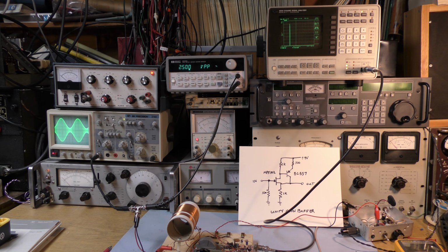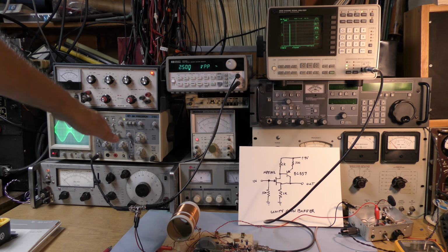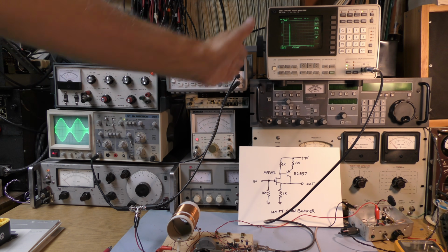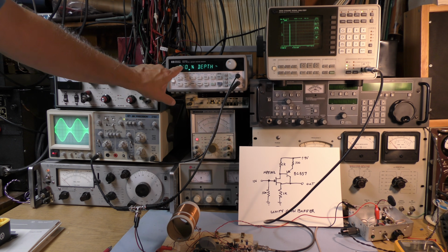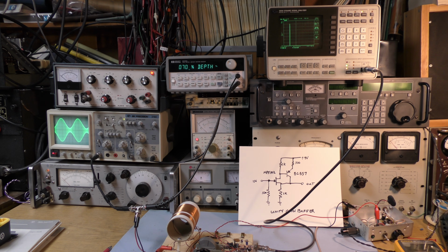So let's now go down into the square law region with the crystal radio, and let's see how it acts with various input levels as we go through the square law region of the diode, and with various modulation indexes. Now, we know in theory that when we are using the squaring method of detection, there's a nasty second harmonic, just like the one we just saw, that will come up. And let's see what our distortion ends up being at the lower levels.